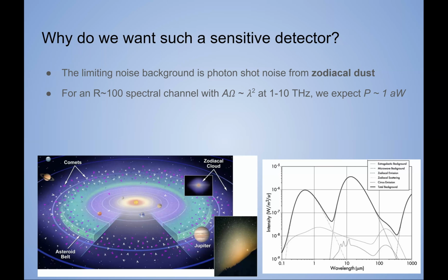Yeah. So I think I understand the readout thing better. It's how often you can do a full band sweep of S21, right? So you're sweeping across your gigahertz-ish range to look for the resonances. So the sine wave you're generating is in the gigahertz, and you're computing its S21, but your readout speed is how often you can do that process, right?